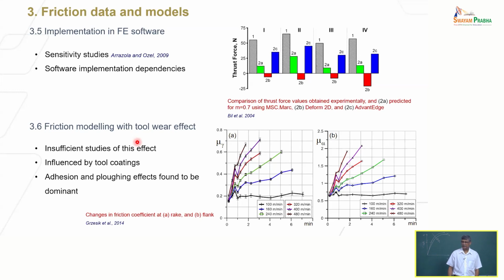Actually, in my opinion, it's a very difficult problem because there are so many stochastic aspects of wear phenomena that it is hard to predict tool wear from first principles, even though you know there are fundamental mechanisms responsible for that wear. It's adhesive wear or abrasive wear or diffusion wear or whatever wear mechanisms that are understood. What combination of these mechanisms is responsible for wear? Nobody knows unless you calibrate. For every tool and workpiece material combination under different conditions, a different combination of these mechanisms may be playing a role.